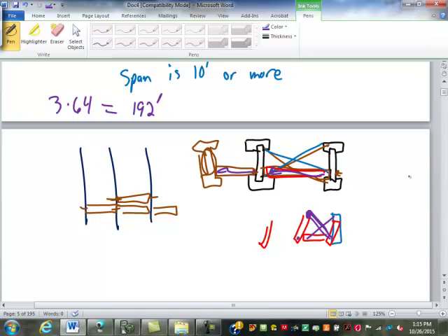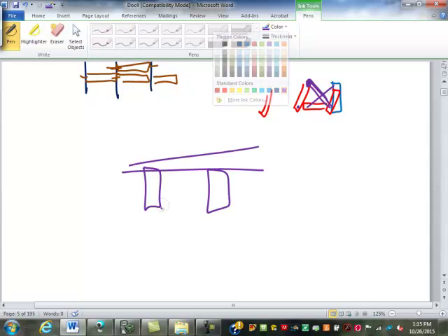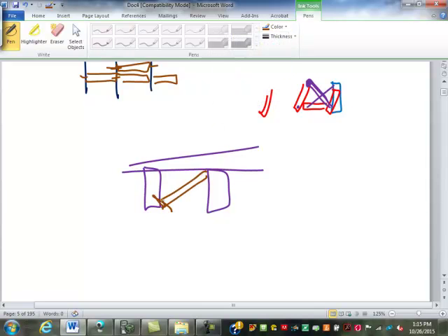And the key to X bracing, I mean, a lot of people think, oh, let's put the floor on first. That way we can just slam this in here, nail it right here. Well, how'd you nail the top? That's what you try to nail through here. But it's a pain. If you do it before you put the floor in, it's a lot easier, I think. But that's my personal preference.